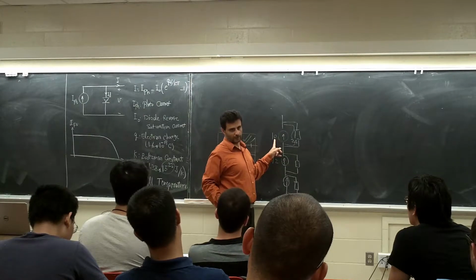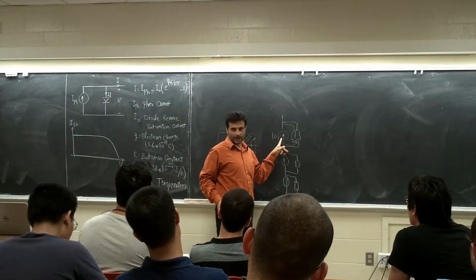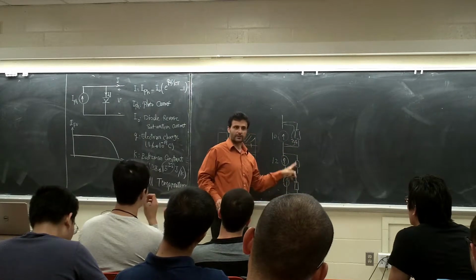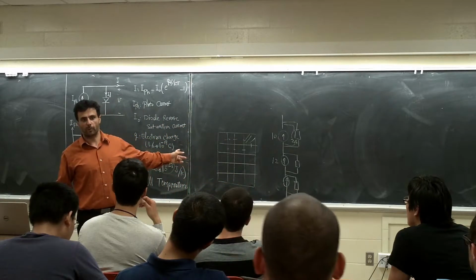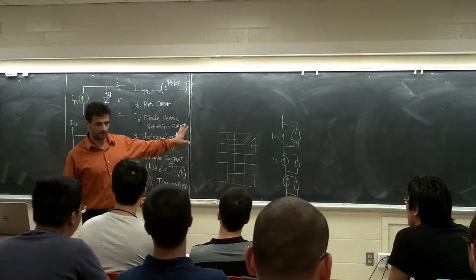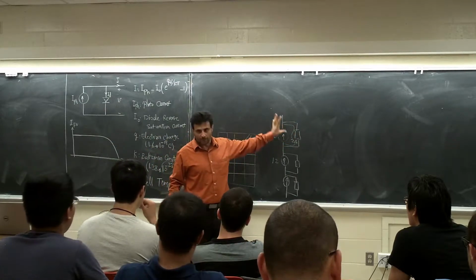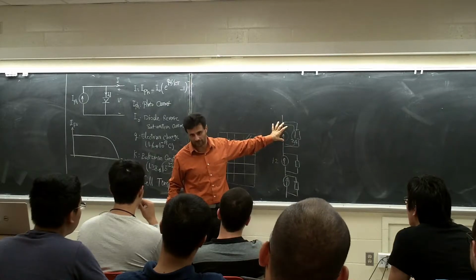10 amps is going to go here. So basically, this one is going to do whatever it can, the best it can. This one can do the best it can. But the problem is you need this box, right? These are costs. They call it cell level maximum power point tracking. We'll talk about this one, maximum power point tracking. But this way, you can maximize each cell by itself. You know what I'm saying?